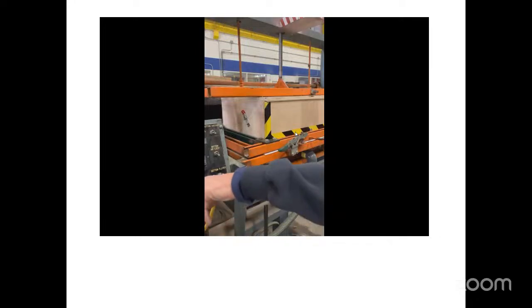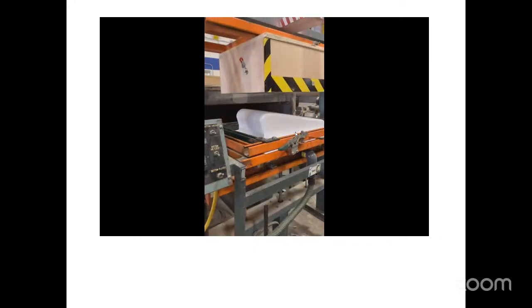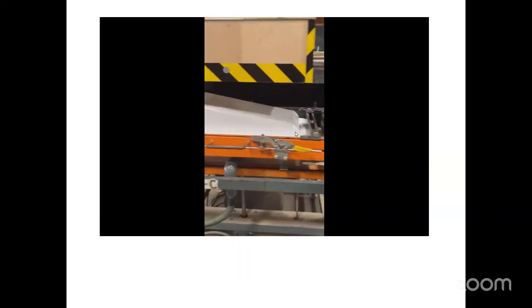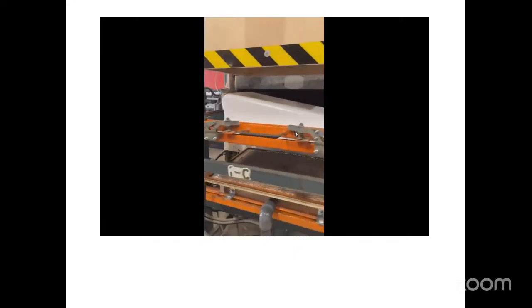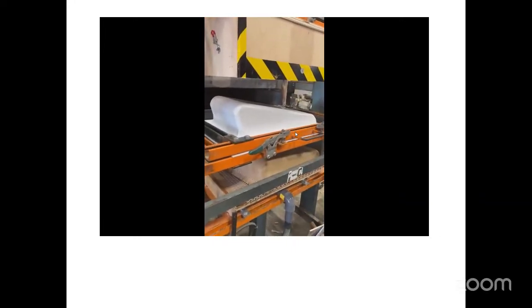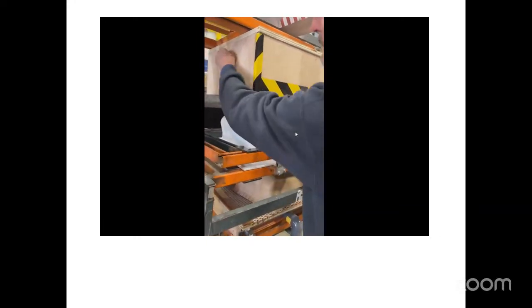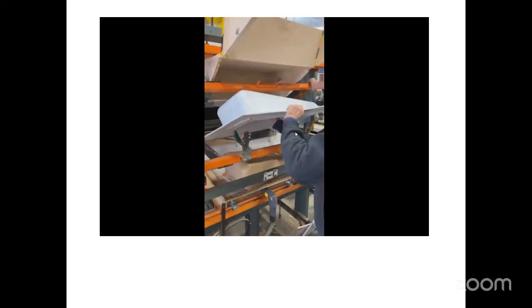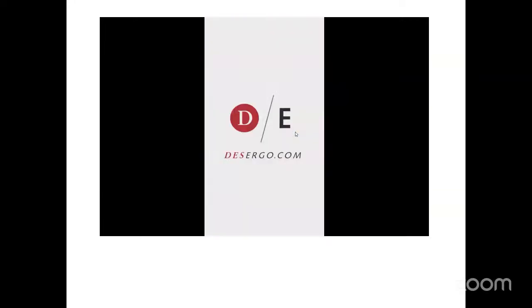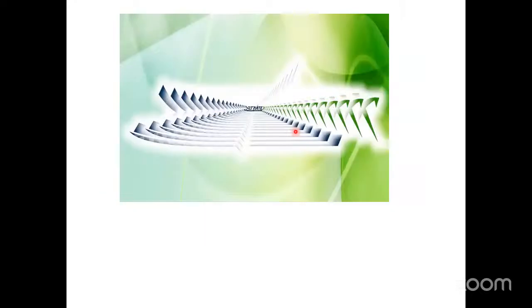If you want the details from the top, then the first method, straight vacuum process, is used. See now, this is a HIPS sheet. The mold is a wooden mold. Now they are opening the clamping and they are just removing the articles. See, the article is a huge one and having all details.